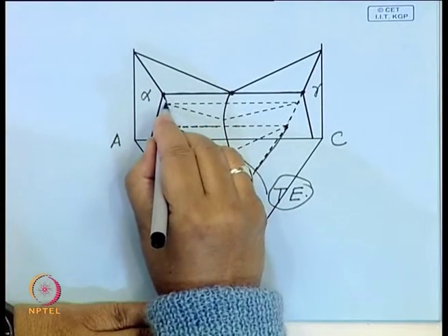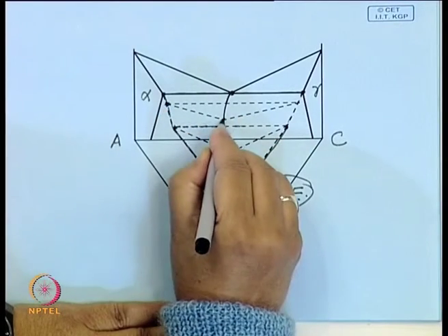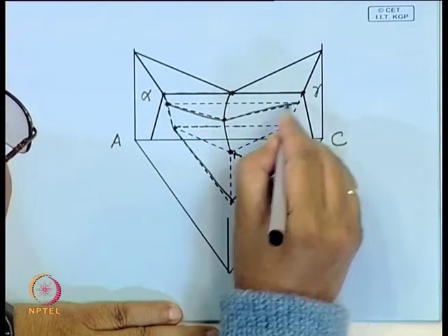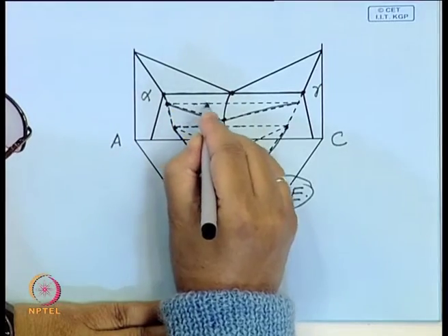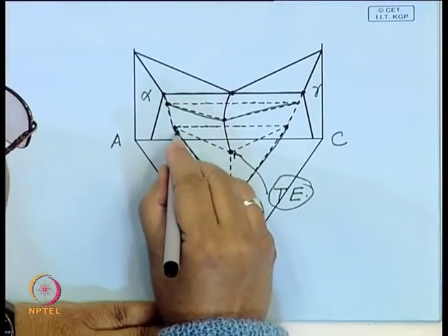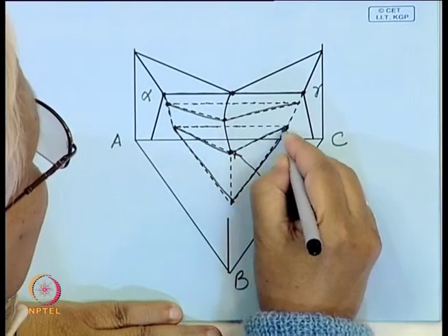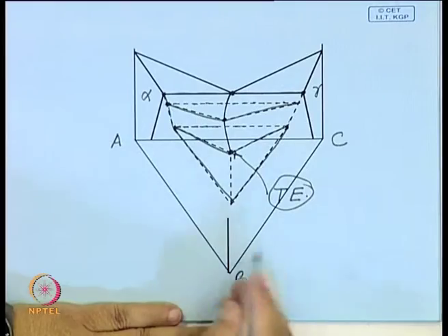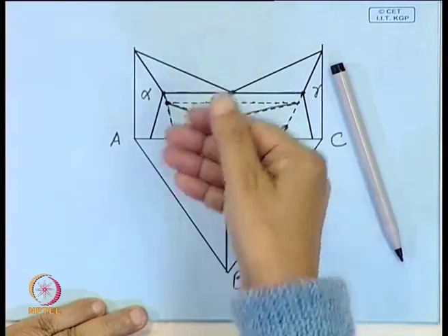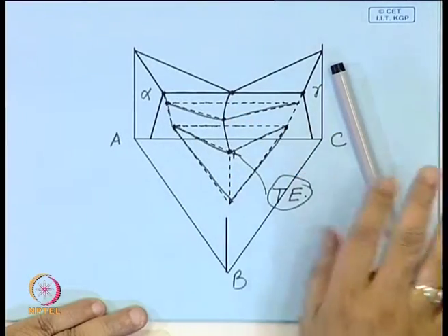Now, you see, what you generate here is one isotherm, this is one point, this is intersecting here, this is intersecting. So, this is a kind of triangular region, and these are the dotted lines which are behind. Similarly, this is another, at this point it just meets that eutectic isotherm. So, this type of triangular plane just comes down and meets the ternary eutectic isotherm.